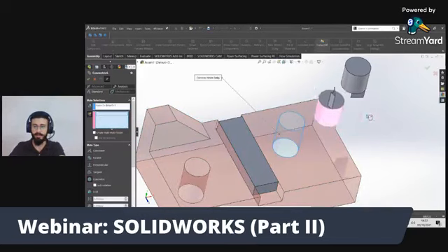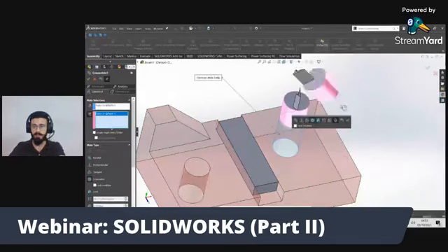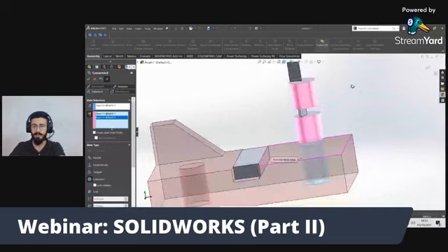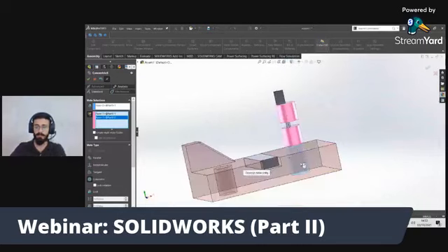And now this is my face, and this is my face. See, these all are concentric to the same face. Multi mates are used, I'm repeating again, if there are a lot of bodies which are sharing one face. Every body has one face which is being mated to one single face.